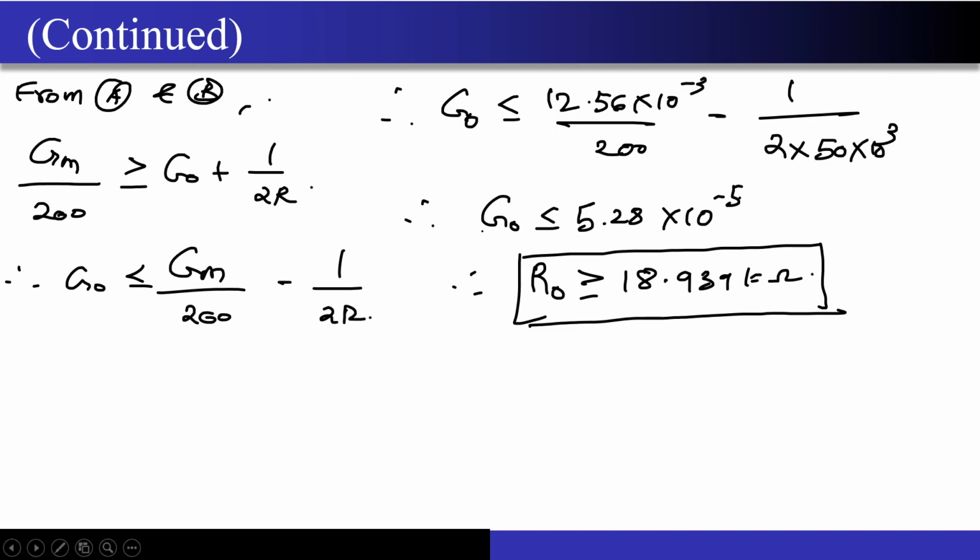So the specs that I wanted on GM and R0, I already got that. So that's very good news. Now one problem is I could have directly used this R0 value, right? For example, if you look at the output impedance of your 5-stage OTA, correct? Now forget about the feedback, because they wanted me to design the non-inverting amplifier from the specs that they have given on the closed loop system.